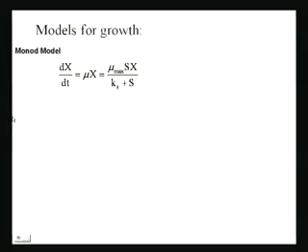So let's go back to what we were doing, that was a digression, I think. What we're doing is the Monod model. This is where it started, the Monod growth model. Let's forget this, just look at this: dx/dt equals mu x. That's my Monod growth model for x. What I asked you is, is this equation valid for all kinds of reactors? That is why I digressed and started talking about the different kinds of reactors. Which kind of reactor is this model valid for? The way I have written it here, you should be able to tell this now. What about other reactors?